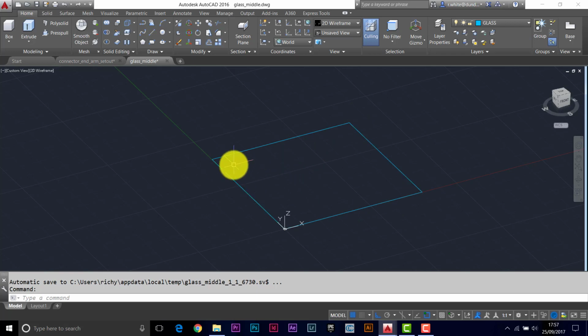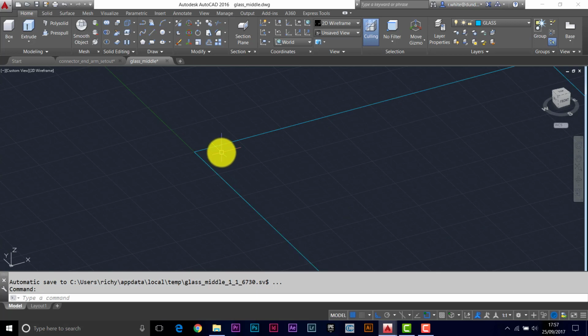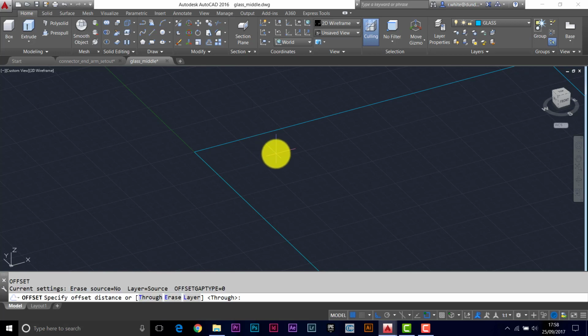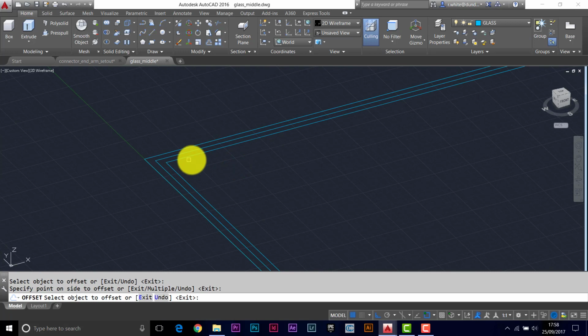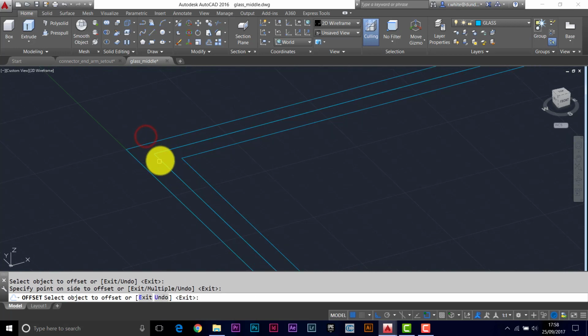So we'll bring this in by 10 millimeters. So we'll end up having a visible 20 millimeter mastic joint. That's quite big, but in the size of a 2 meter panel, it's really not that much. So it keeps the numbers nice and round as well. So if we come in by 10 millimeters, and then another 10, and then bizarrely we want to go back 10, so we'll end up with 2 rectangles, 2 squares at this point, but 1 each in these.